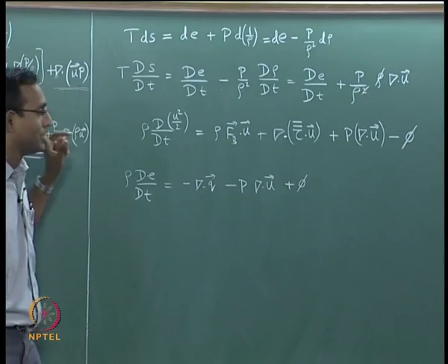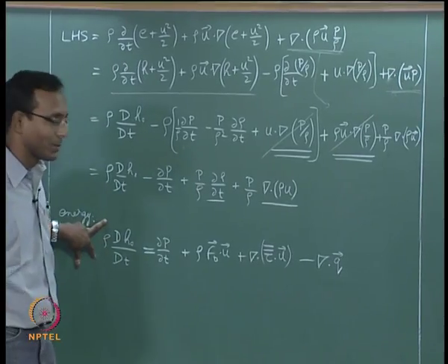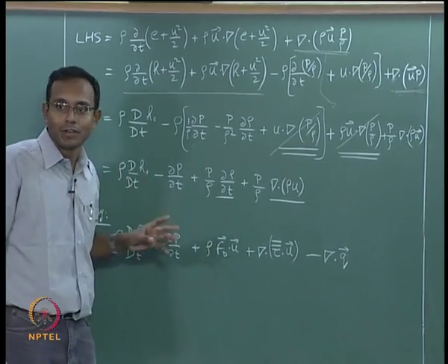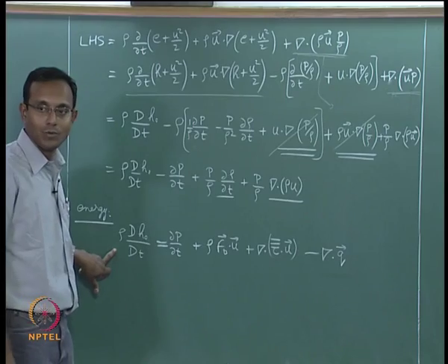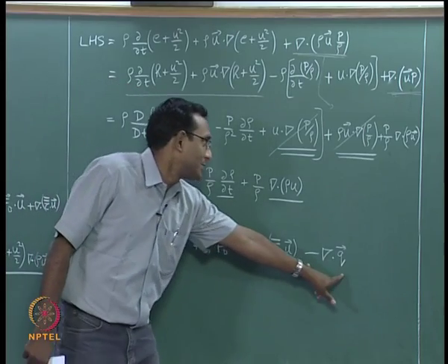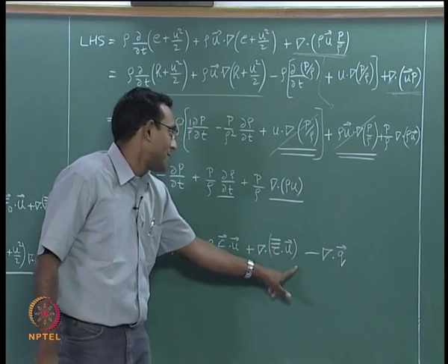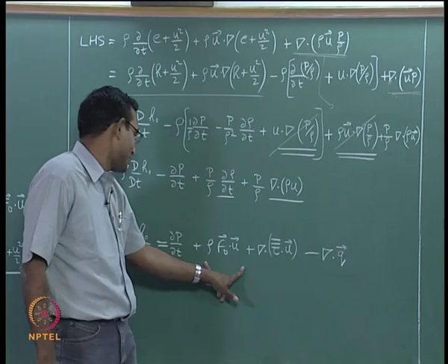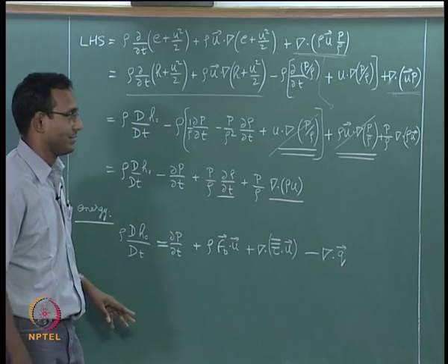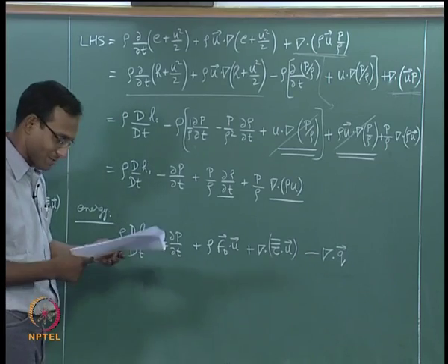If you look at the total energy equation which we had before, I will go back to it once more, that is this one, we find that there is no phi in this particular thing. Why? It is just an internal rearrangement, it is taking from one pocket and putting it into the other pocket, so it is not there at all. This is the net energy, overall how much do I contain. In here, this part is sitting only in my internal energy equation, this part is sitting only in my kinetic energy equation, this also sitting only in my kinetic energy equation, this term is hidden somewhere inside, in that p dot del u kind of term. We won't worry about that part, it will come up now.